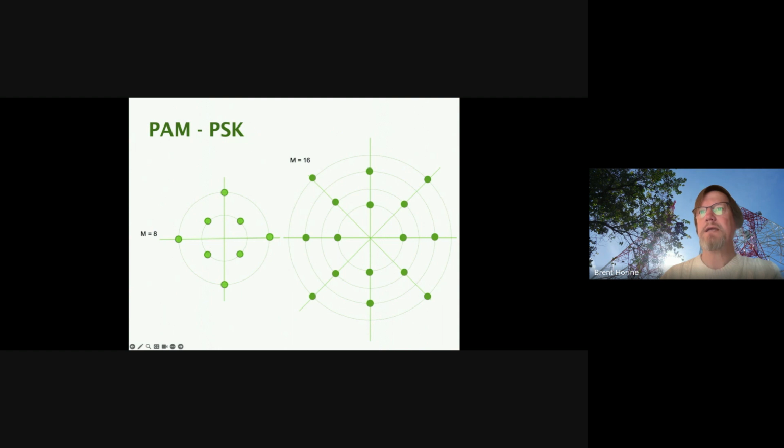And here, these guys look more like a square. They're really the same. It's just they're rotated relative to each other, right? And of course, this one is smaller amplitude. But if this inner circle was rotated the same as the outer one, then we would be really close at some of these points here, right? So like this constellation point might be right there, and then we'd be close. So we're arranging this so that we are still trying to get maximum distance between all these constellation points.